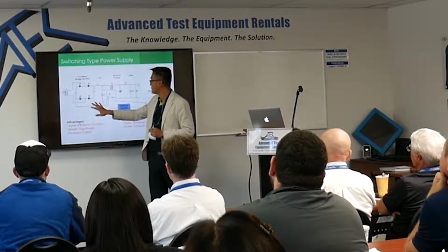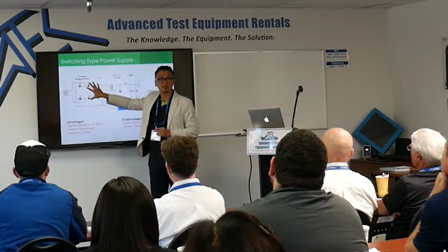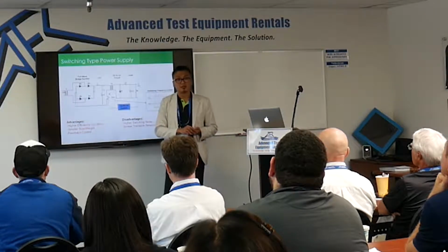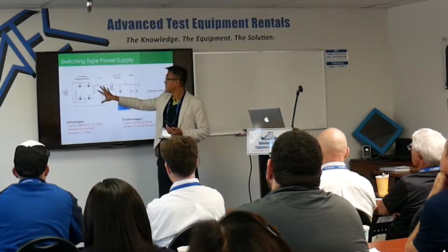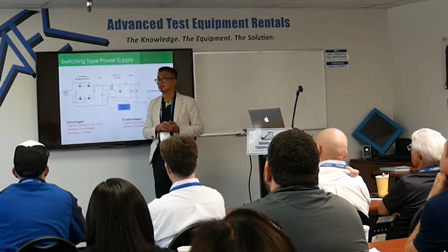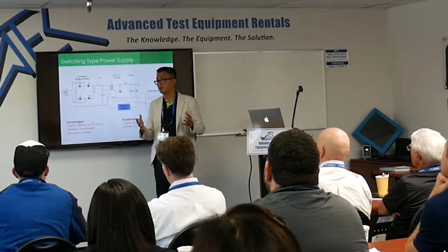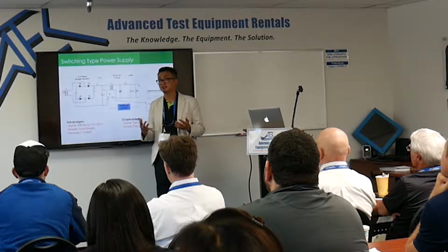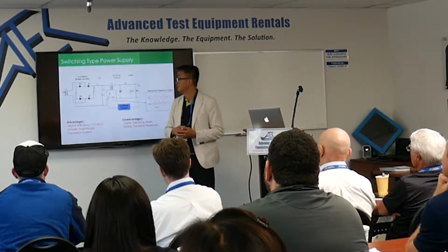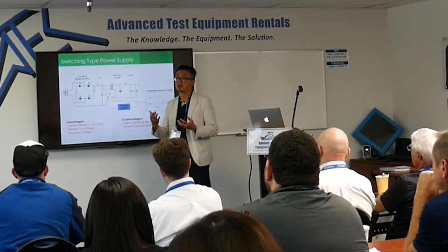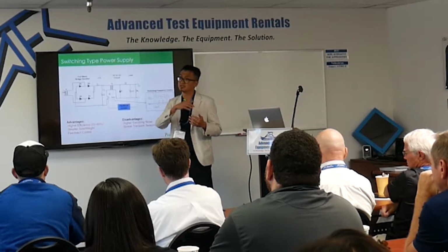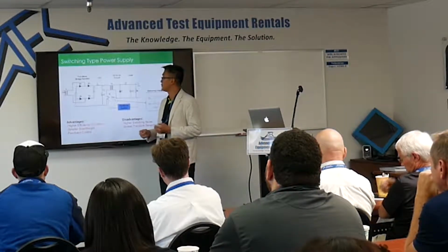Also, some people have decided about the rectifier. They have 6 poles or 12 poles. So how many pulses the rectifier has will affect the input power factor. Nowadays some people are concerned about input power factor, or they don't want the grid system to be polluted by the switching power supply. Too many switching power supplies will make a lot of switching noise in the grid systems.